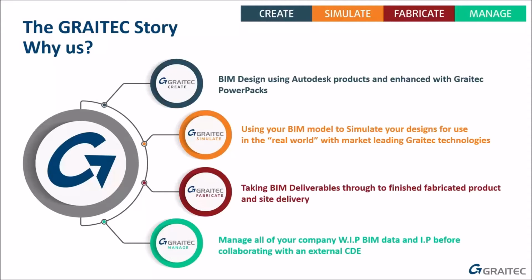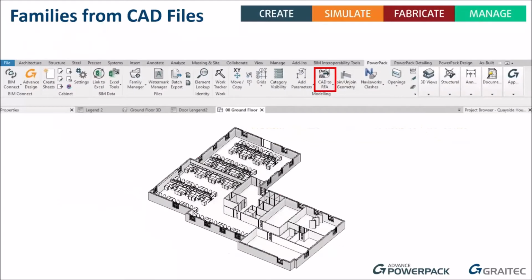So the tool that we're going to be looking at today creates families from CAD files. Okay, so we have a little button here on our modeling. As I say, it's known as the CAD to RFA tool. What this is basically going to do is allow us to use CAD files within our Revit projects and very, very quickly turn them into Revit families. Okay, and it automates the process.